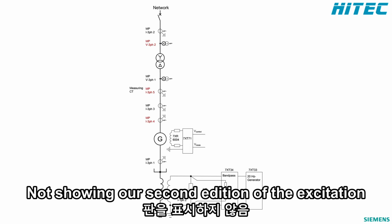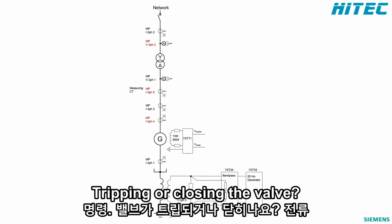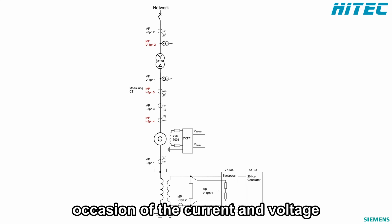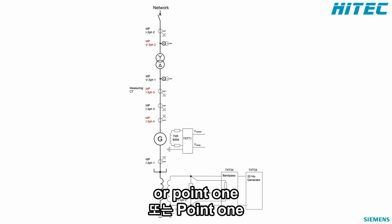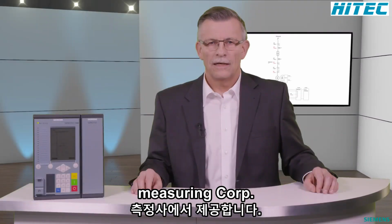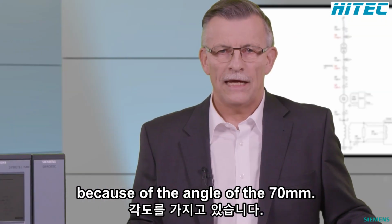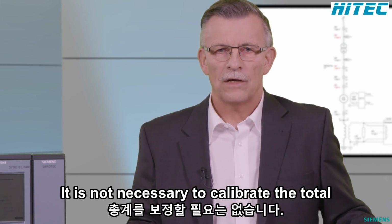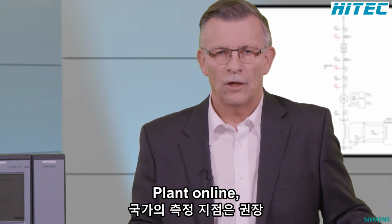Not shown are the attenuation of the de-excitation and the command for shutting down the turbine by emergency tripping or closing the valves. You can see the quantity and the location of the current and voltage transformers. Reverse power protection is provided with a separate class 0.1 measuring core. This measuring core has a very small angle error of 10 minutes. And because the angle error of the 7UM85 can be neglected, it is not necessary to calibrate the total angle error in the over and under excited operation of the power plant online.